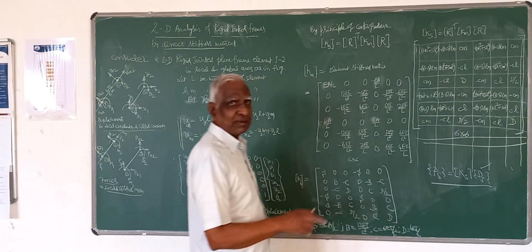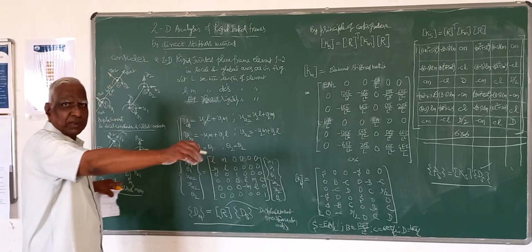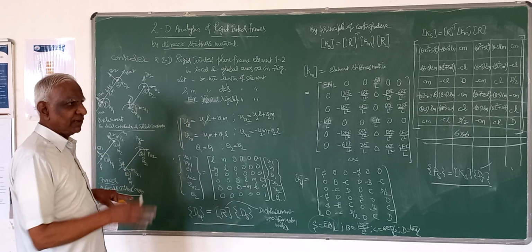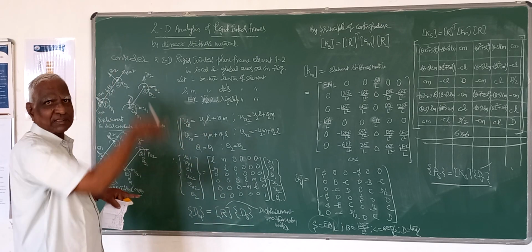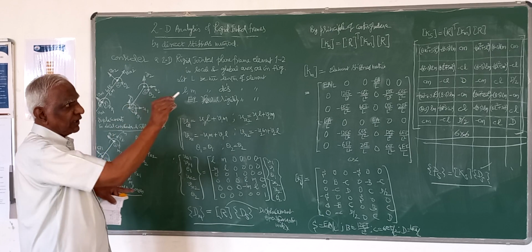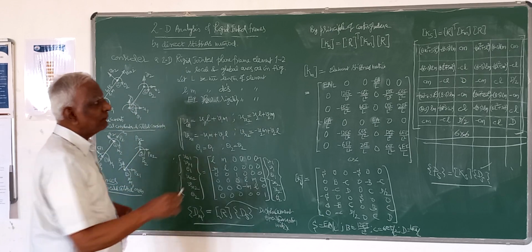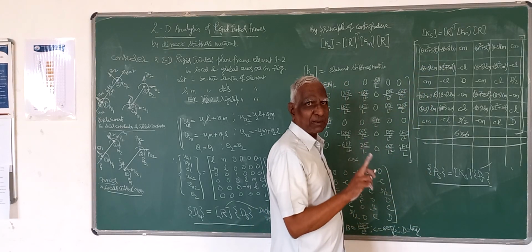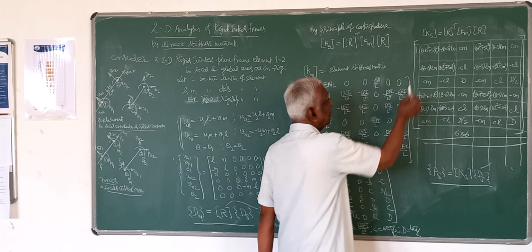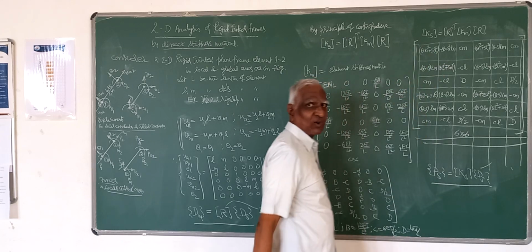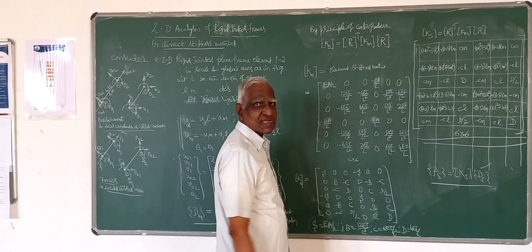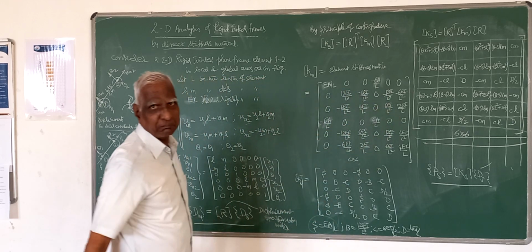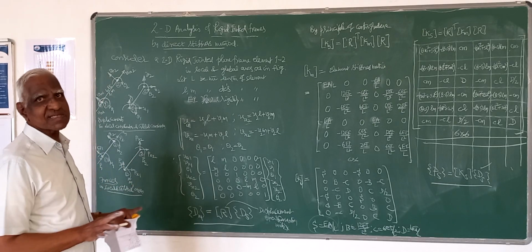And also, if it is a perfectly horizontal beam problem, with all members lying only in the horizontal plane, the direction cosine with respect to the y-axis, small m, will be 0. So small m will be 0, only small n will be 1, because it is cosine 0, that will be 1. S also will be 0, and automatically things will get simplified. So it will come to only this much for a beam problem which is axially rigid.